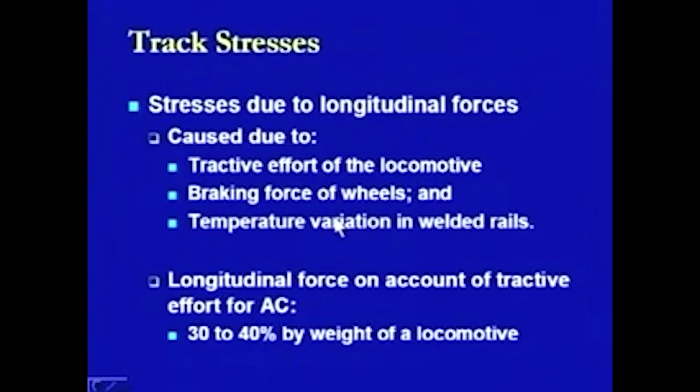The another case is the stresses which are caused due to longitudinal forces. Now, when you are talking about the longitudinal forces, there is a train or the wheels which are moving in a certain direction on the rails. Then there are certain things which can happen during the movement. One thing is that you are in a standstill condition and you start moving. That is where the tractive effort of the locomotive comes into picture.